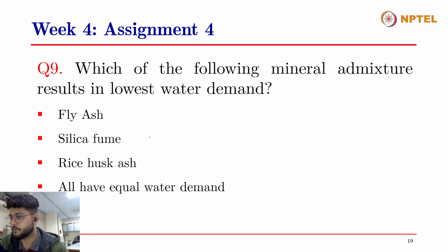Okay, sir. Thank you. So it ranges around 5 to 15%, because beyond that it increases the issues of workability loss and all of that. The fresh properties are affected quite highly, and again, as we mentioned, there are issues of shrinkage, creep, and so on. So we tend to keep the amount of silica fume within that range. Okay, sir. Thank you. Anybody wants to answer this question?